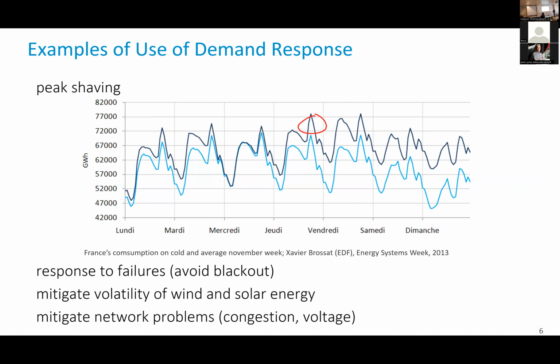A blackout is very bad. People can die from a blackout, right? People who had a medical condition that necessitates some help, and the hospital doesn't work, the emergency system works partly but not fully on diesel generators. That's very bad. So we want to avoid this. How do we avoid this? Of course, we plan in the grid for reserve. We will talk about reserves in a second. And those reserves, so we put a safety margin, but part of the safety margin can involve reducing consumer load here.